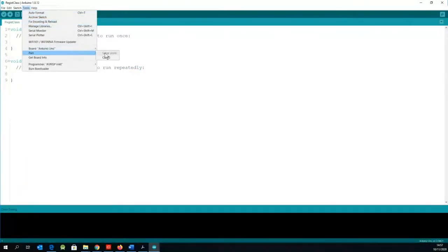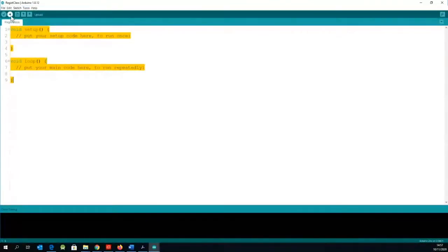Afterwards, you select the right USB port, which in this case is COM3. If I have Arduino connected, it may pop up with a different number, and you connect to it. Then you just run your code, compile and upload, and it will upload it to the board. So that's the final stage. It's just transferring the circuit and other things that we have to the board. So anyway, all we have is 2 functions, no code in them.